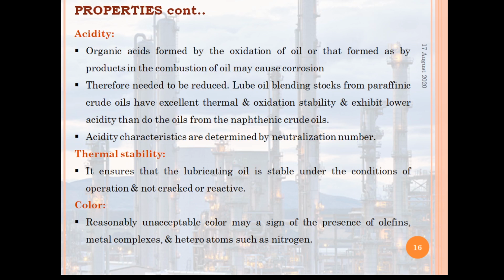Then the acidity characteristics are determined by the neutralization number. This is the process by which the acidity can be measured. Thermal stability ensures that the lubricating oil is stable under the conditions of operation and does not crack or become reactive, meaning the oil is stable up to a certain temperature.